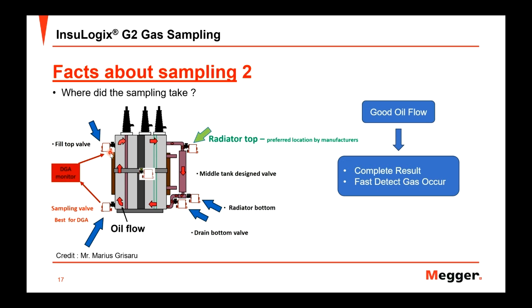Some people or some of the group don't want to climb up and do the sampling above the transformer. It's quite hard to do. So normally we don't sample at this position, but normally it is a very good position to sample. And the next is the drain valve. If you're sampling from the position that is far from the heat exchanger, okay, this is the very good or the best position for sampling because it is the easiest.